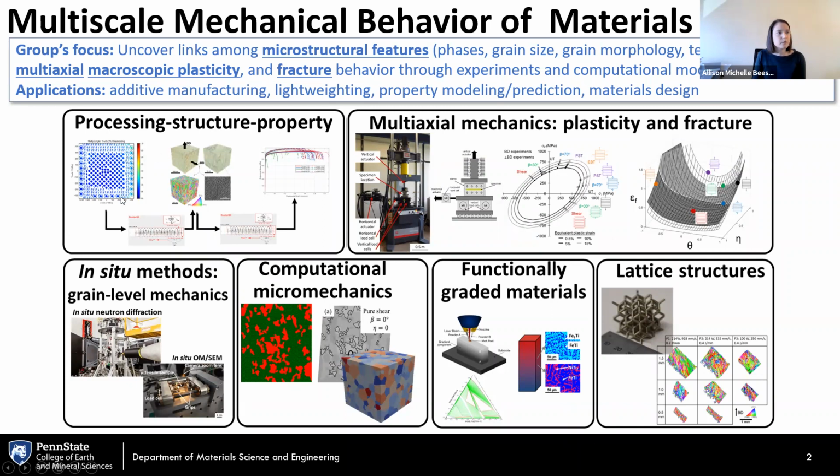And this is some of the recent work that we're doing in terms of using in situ processing signals during additive manufacturing. So this is during a powder bed fusion build, using computer vision technologies to try to then link those signals to the microstructure and the mechanical properties, with the idea being that then you could monitor your process and have some control where you identify that you've formed a defect and you can fix that during processing by adjusting parameters.